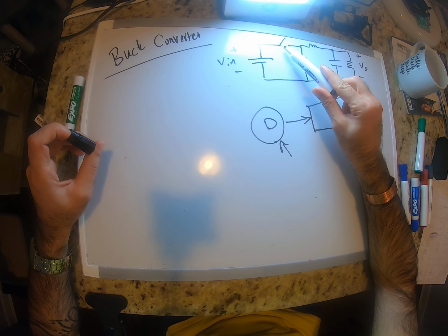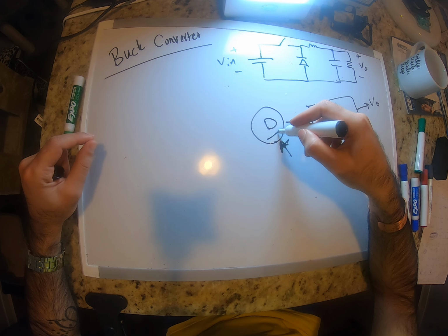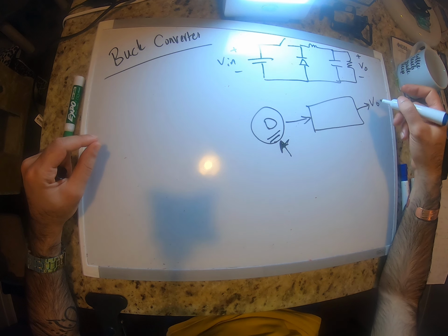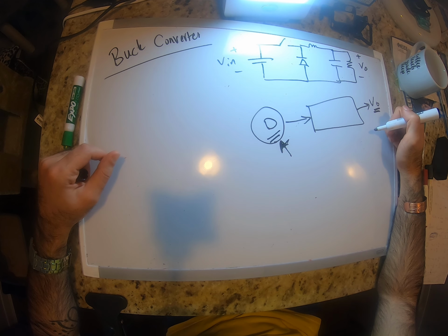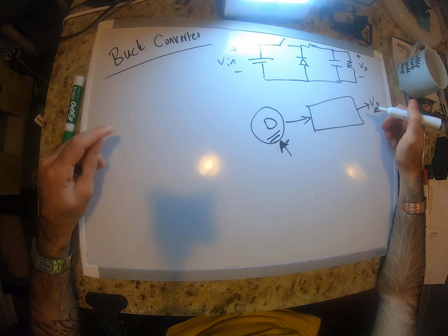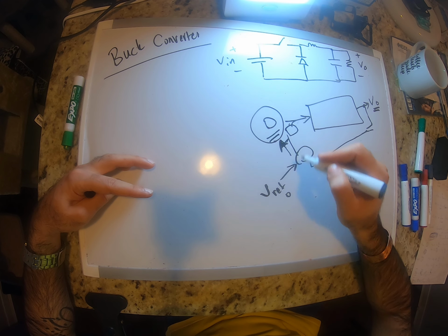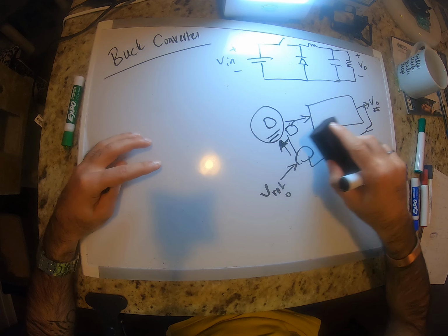So there's no guarantee that if you have an open loop system and set your D to the value that you calculated, you get the output that you desire, right? So we want to have a feedback control for this so that we can measure the output, and based on the difference between this output and the reference output, we just want to be able to adjust the duty cycle, right? So this is what we want to do.